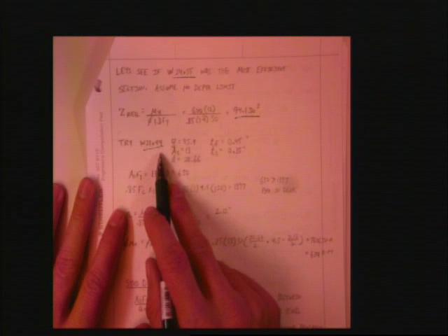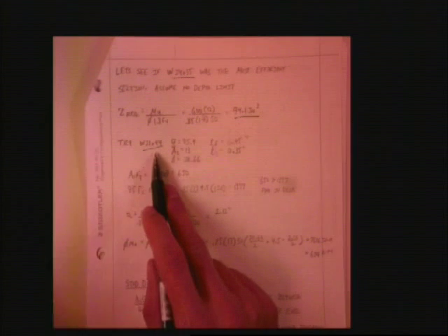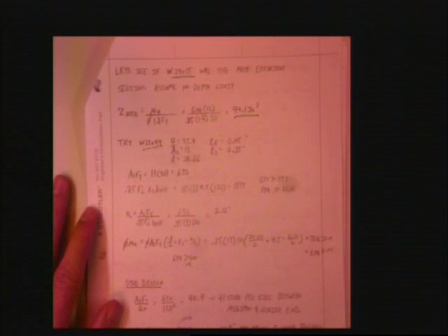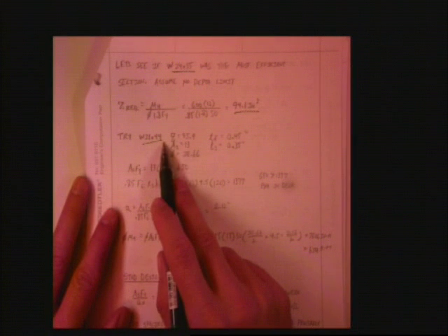Do I need to worry about L sub B on composite girders? Why not? Compression blocks at the top. That's right. But we learned about L sub B. L sub B is the unbraced length, right? And you are 100% right in the previous girder. We don't have to worry about L sub B because we're always in compression, right? In this problem, though, we don't necessarily know that's where we're at this point. So in a sense, we're assuming that L sub B is not an issue. We're going to have to figure that out when it comes up later on.